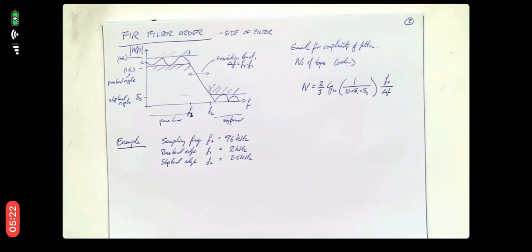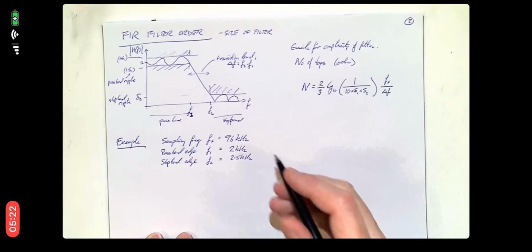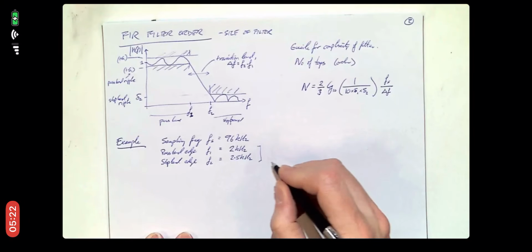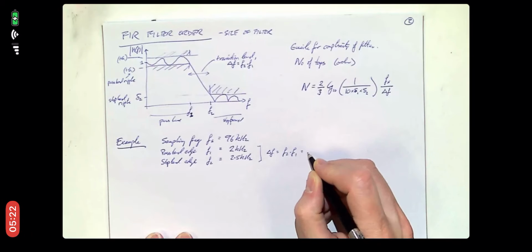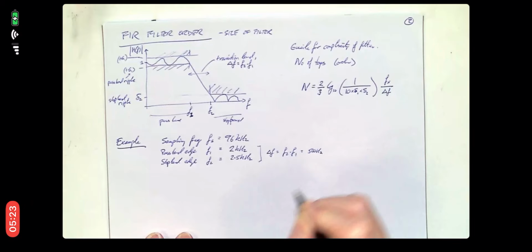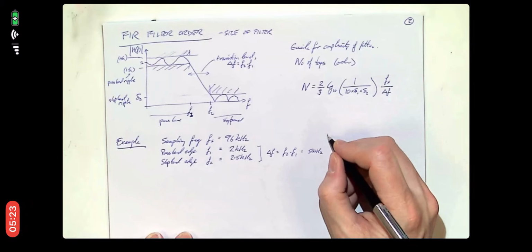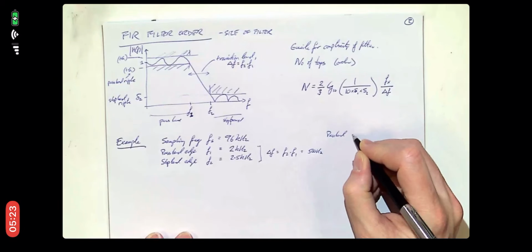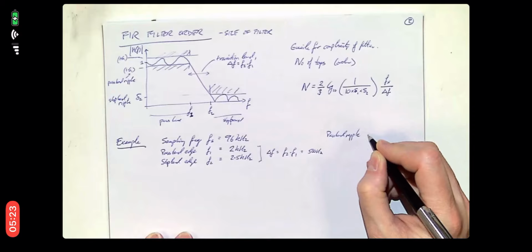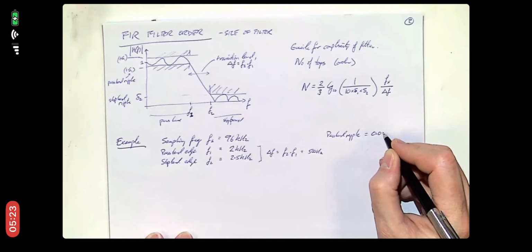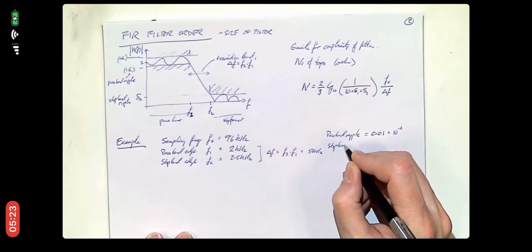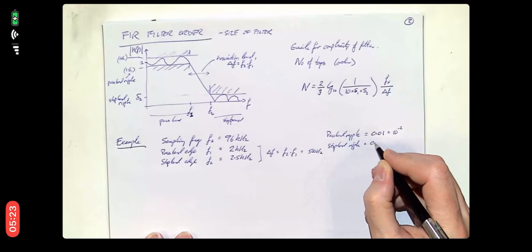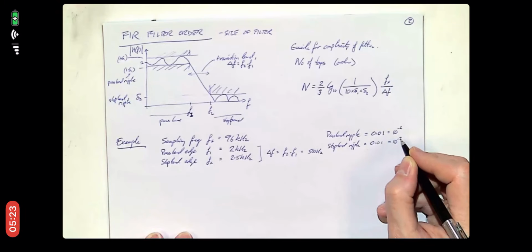So we're going to do some downsampling, so we're only going to keep the stuff up to 2 kilohertz. So what this means in particular is that our delta F, which is F2 minus F1, is 500 hertz. And we're also going to have pass band ripple of 0.01, so 10 to the minus 2, and stop band ripple 0.01, so again 10 to the minus 2 here.